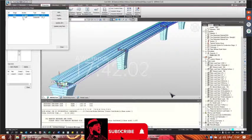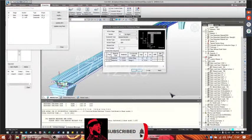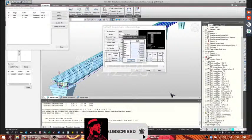Here we have the two beams, the two main beams. Here, practically, we choose to activate the concrete part of this section in stage 1, to avoid that the simultaneous presence of this part and of the slab element brings us to a double stiffness. We eliminated here, in scale factor, the torsional inertia in the transversal direction, y-axis.